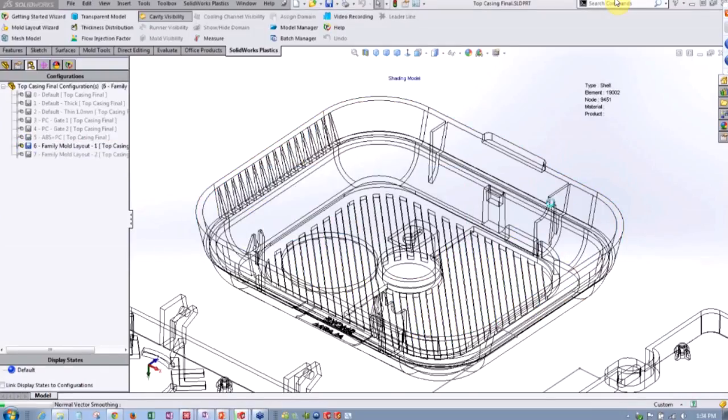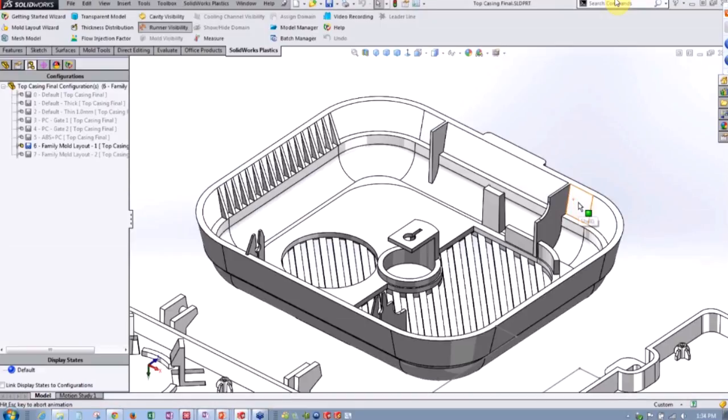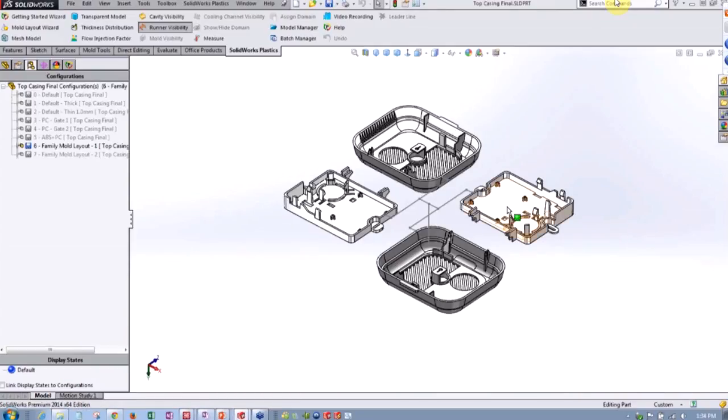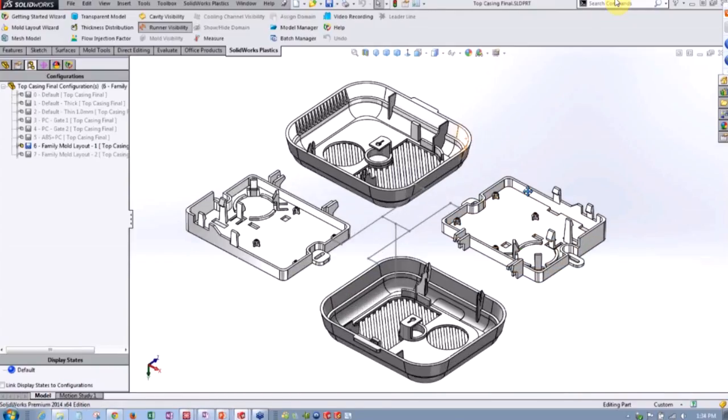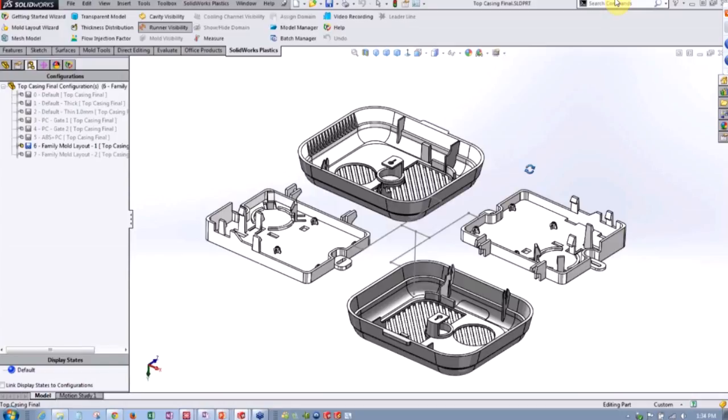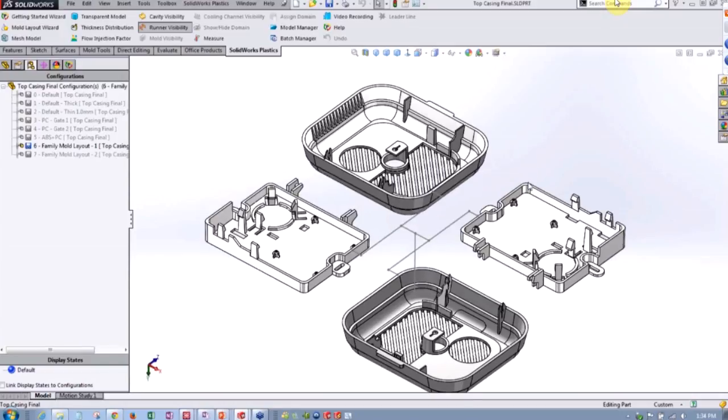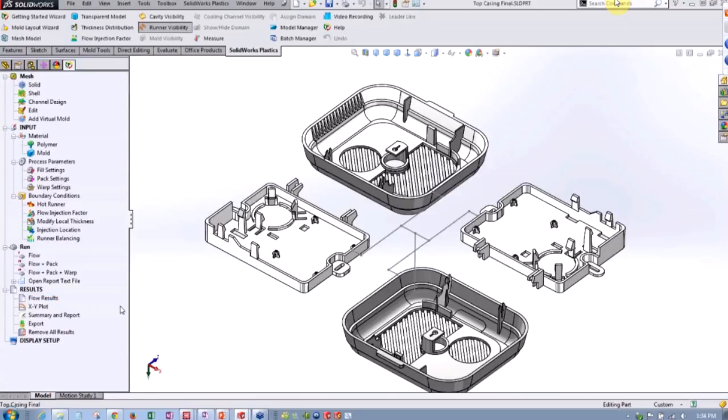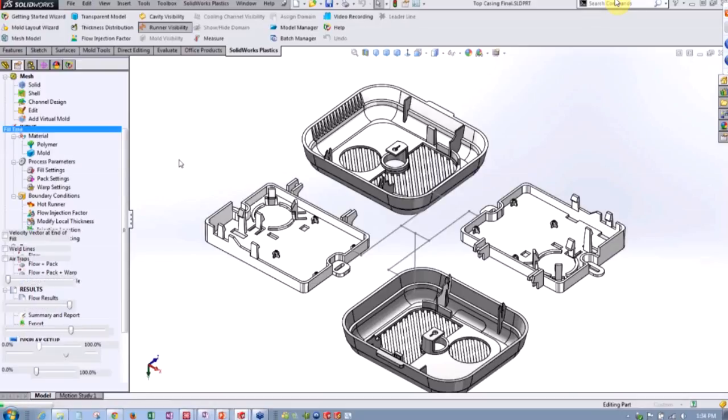And this configuration has 2 of our covers and 2 of the bases for this smoke alarm that we'd want to run in one shot through a mold. Just in terms of efficiency, this is going to be a much better way to go. It's the same plastic mix, so it gets the same density, same mechanical properties, same color, same surface appearance. Lots of good advantages to having everything all in one